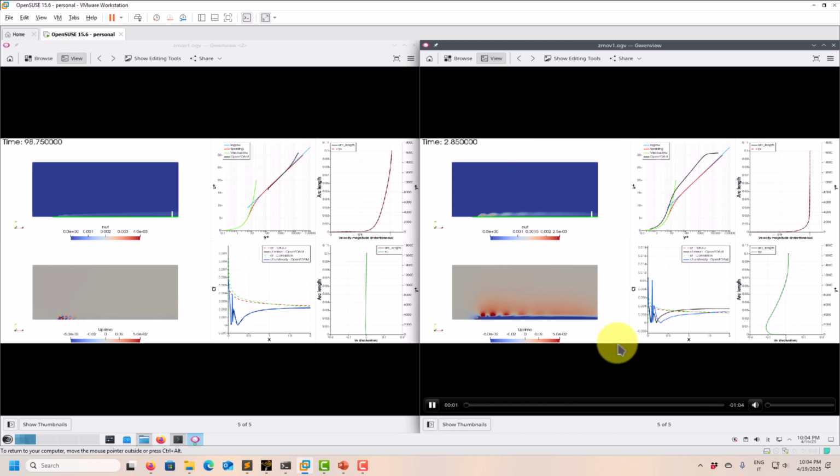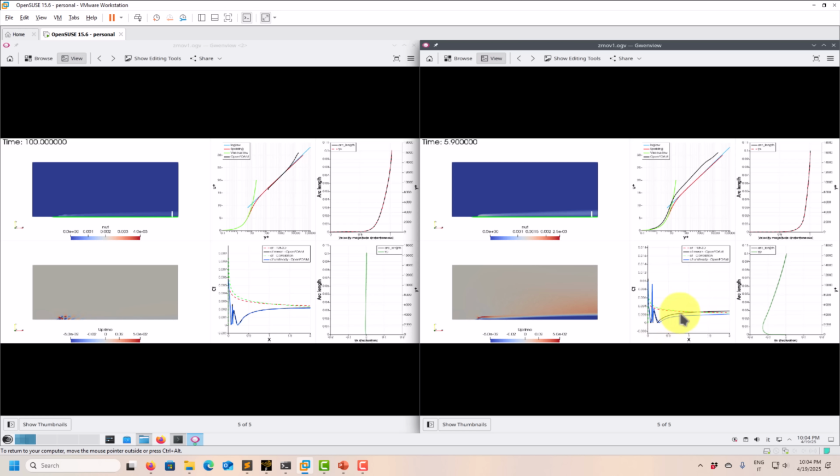So you start and look at instantaneous, and the black line represents that mean value. And look at that, it's still changing. So I cannot say that I can stop here because it is changing my mean. Also my mean here, it is changing in time. So you should monitor. In this case, we have monitors here, but it can be anything.